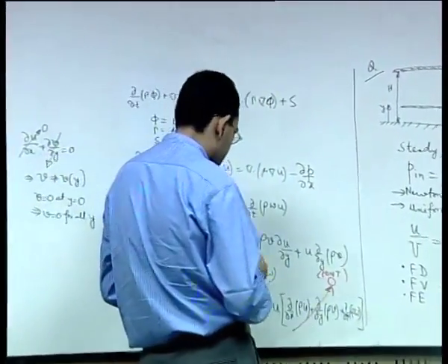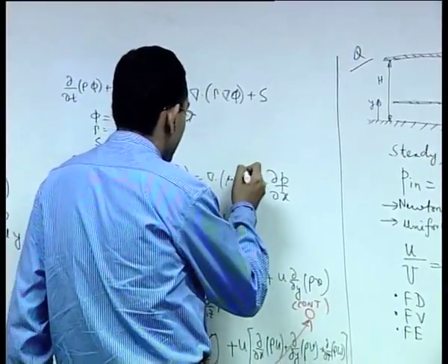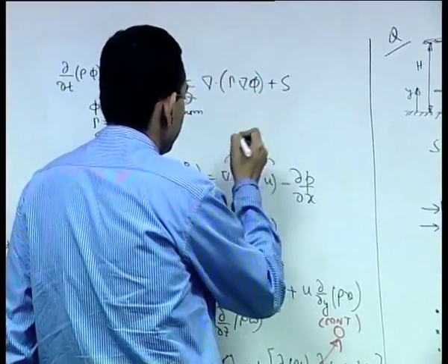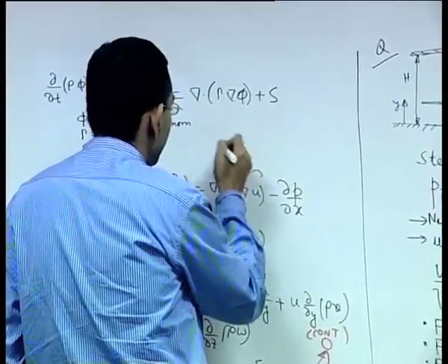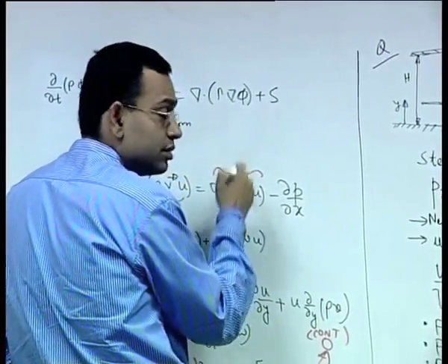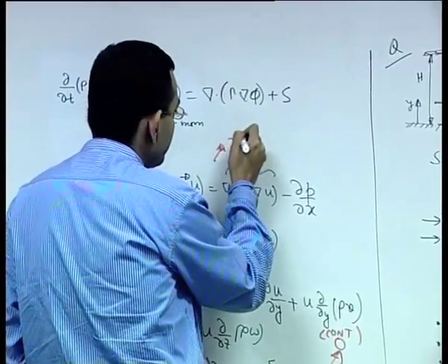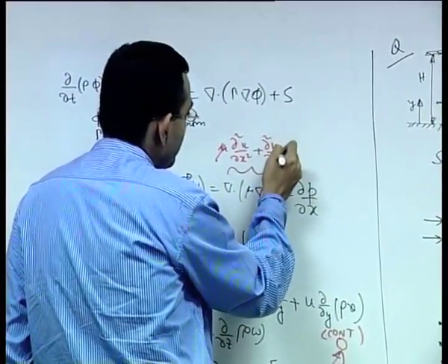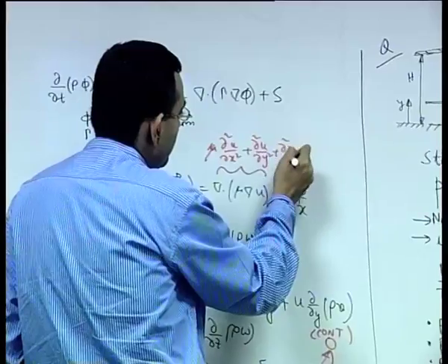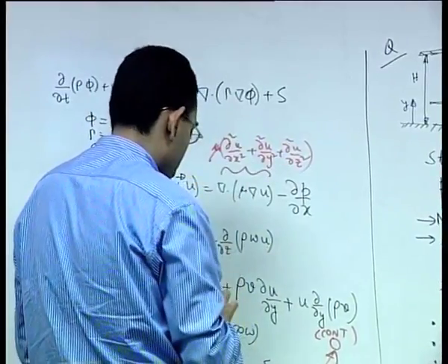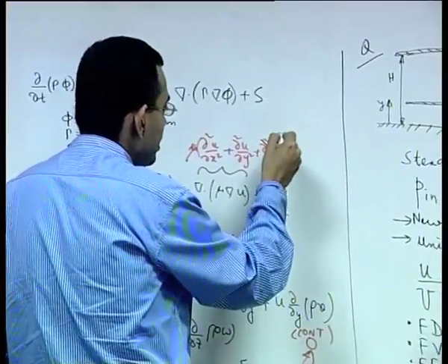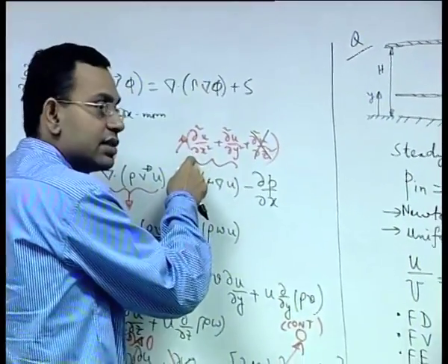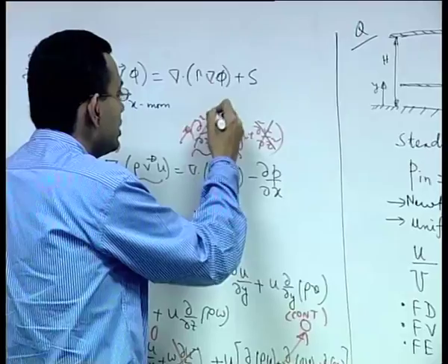Right hand side, if you simplify, mu is a constant which is given. So, it will be mu, and because of 2-dimensionality, the last term is not there. Because it is fully developed flow, del u del x equal to 0, so its second order derivative is 0.